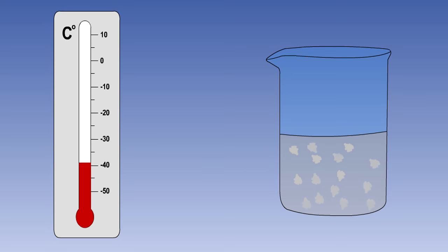As the temperature drops further, the hydrocarbons with slightly lower freezing points start to solidify, and so on as the temperature continues to fall. The waxing point of a fuel is the temperature at which wax crystals begin to form. Jet A1 has a waxing point of -50 degrees Celsius, so waxing is only a problem for aircraft operating for prolonged periods at high altitude in very low temperatures.